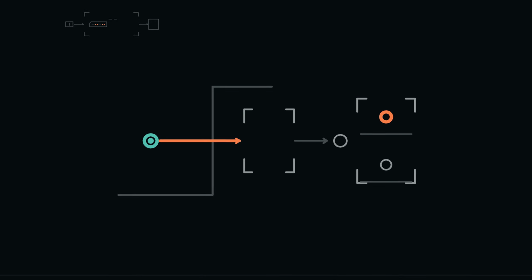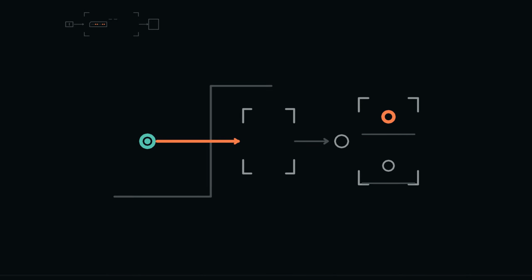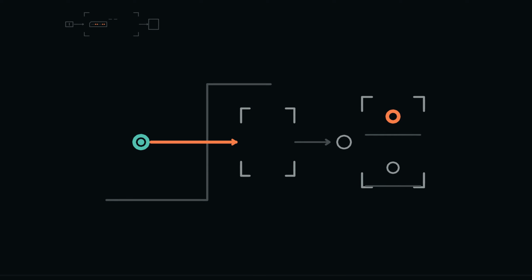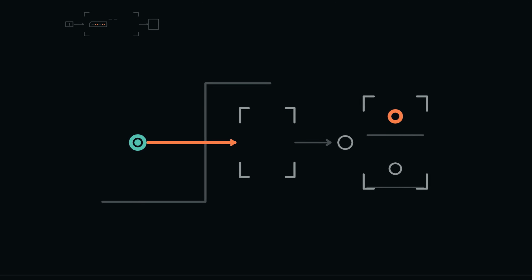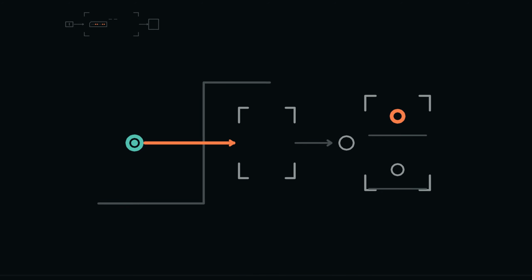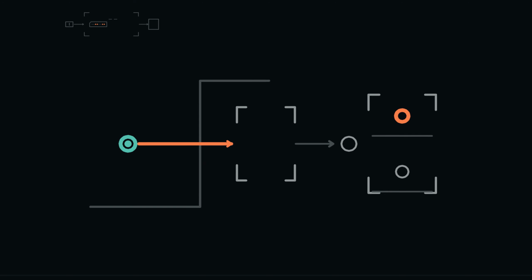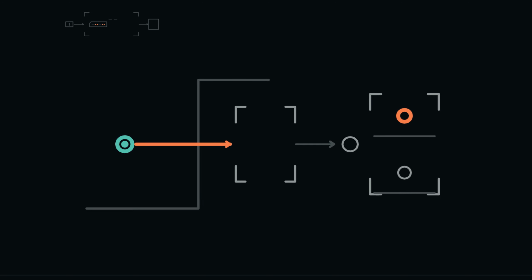Use an edge-triggered storage model with input D and stored output Q. Between active edges, changing D does not change Q. At each active edge, the element captures the accepted value at D. After a finite clock to output delay, Q represents that captured value and holds it until a later active edge.